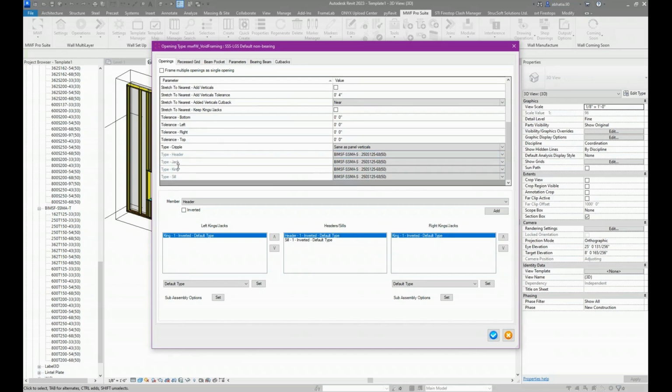And then you'll notice that these are grayed out, right? Since these are grayed out, that basically means it's going to use whatever's specified inside the Revit template. So what that means is I can add the number of members in here, and also the orientation of the members, and then I can tell it to use the members that I've specified inside my template. So then I can use this marker for a 6-inch, 4-inch, 3-inch, or 3 5/8 inch, and a 1.62 wall, which is 1 5/8.